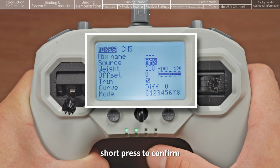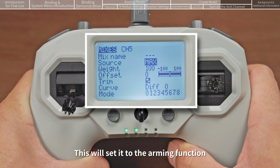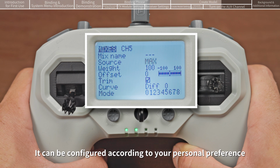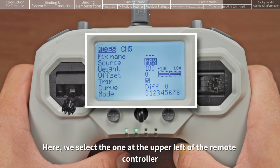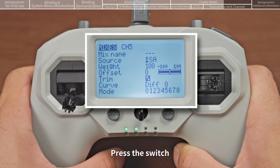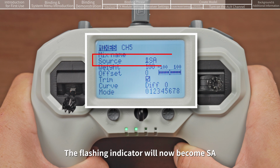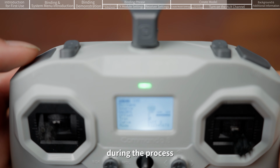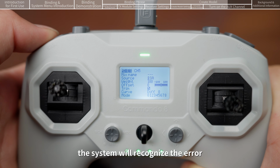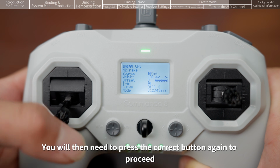Short press to confirm. When the rear indicator starts flashing, move the switch you wish to assign. This will set it to the arming function. It can be configured according to your personal preference. Here, we select the one at the upper left of the remote controller, SWA2 position switch. Press the switch. The transmitter will now automatically detect the switch position. The flashing indicator will now become SA. If you happen to press an incorrect switch during the process, the system will recognize the error. You will then need to press the correct button again to proceed.